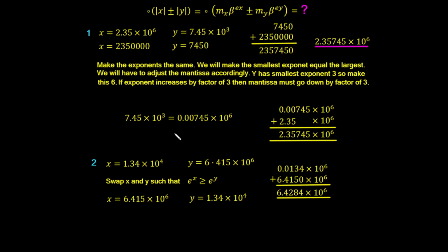But in order to cut down that amount of circuitry, we only need to ensure that we swap the values here, x and y, at the inputs to our circuit. So this ensures that our circuit only ever has to increase the exponent and decrease the mantissa. So it simply makes the circuit smaller and a much easier and neater design.